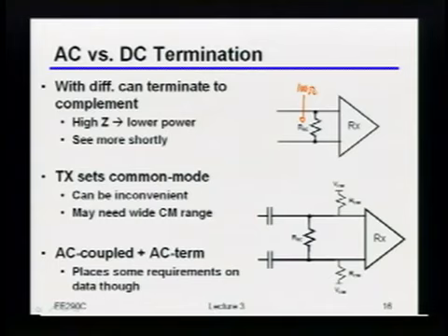So does anybody happen to know how you can make this structure still give you a reasonable common mode termination? I'll give you a slight hint: it'll only work at least over a certain range of frequencies. Yeah? You split the 100 ohms into 50-50 and put a large resistance to common mode or directly connect to common mode. Okay. Well, you almost... So which one of them is it? You said I can split that 100 ohms into two 50 ohm resistors. That's good. Now what do I do?